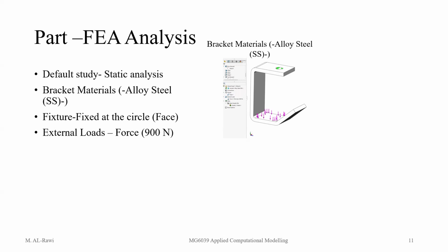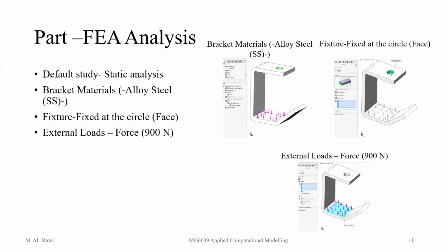to solve this problem for engineering, I need to know the material properties, because it's using Young's modulus, the elasticity and everything. I need to know where it's fixed. This bracket is fixed like a screw, let's say it screws to the wall as an example. And I need to know the load applied to it. How much load? 900 newtons. This, by the way, is not a point load, it is a UDL, uniform distributed load, for that surface area where we apply it. If any question, please feel free to ask. What's next? So that is all.